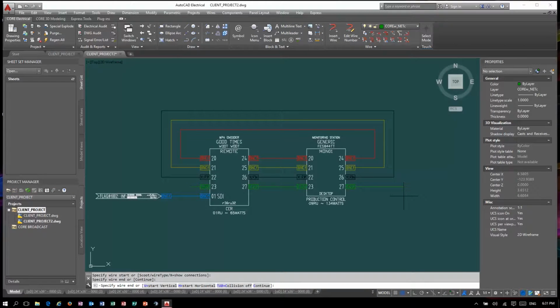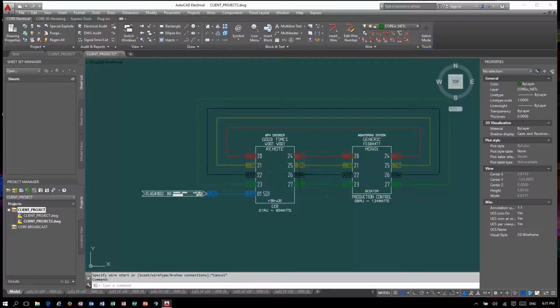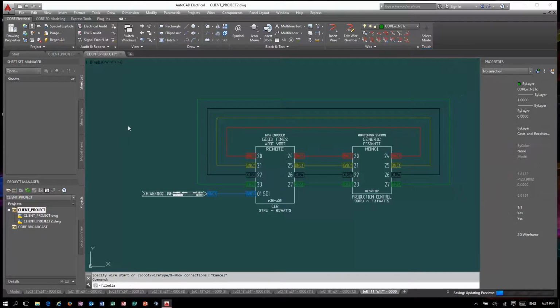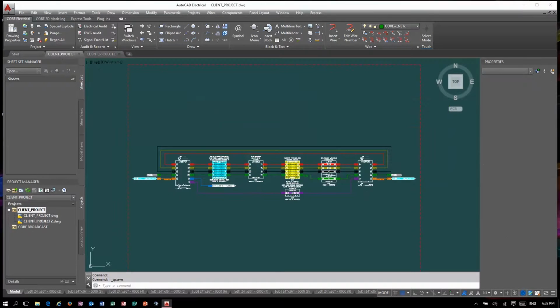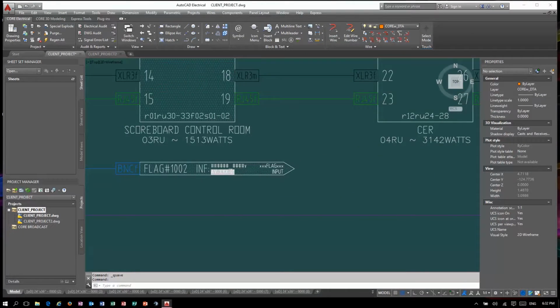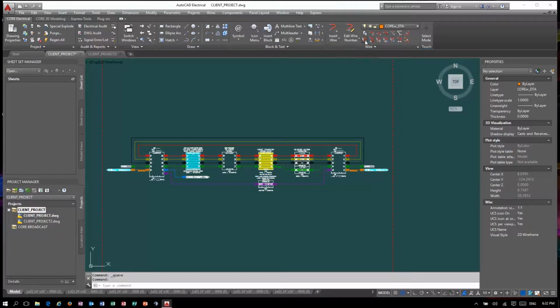The interesting thing about this tool is it has two modes of operation. One, it can automatically assign a fixed variable for every wire number, which would prevent auto-updating of that number in the future. Or it can self-assign and re-update that number depending on drawing layout. If the system variable was set to fixed, the only option you have available to you is editing each wire independently. It's now time to auto-populate the wires across the entire drawing set using the Insert Wire Numbers tool.